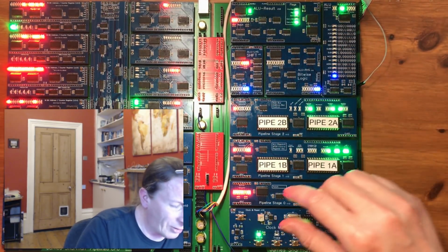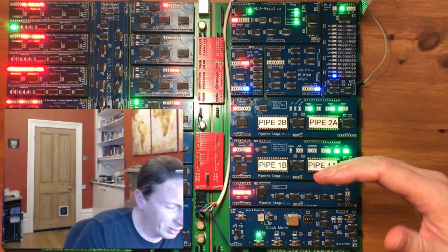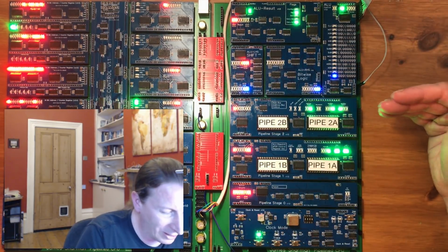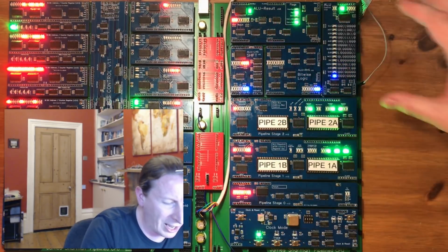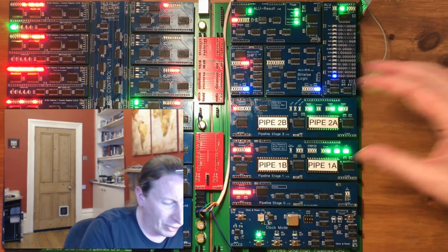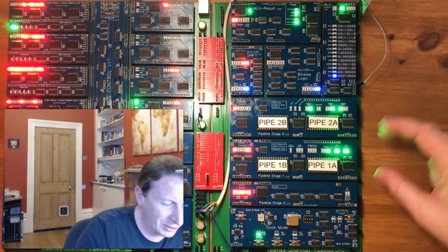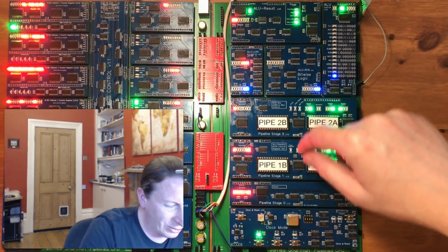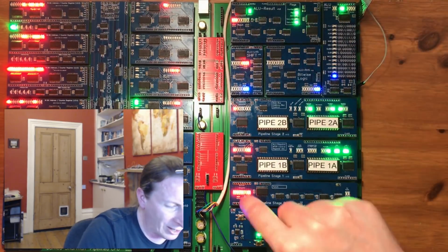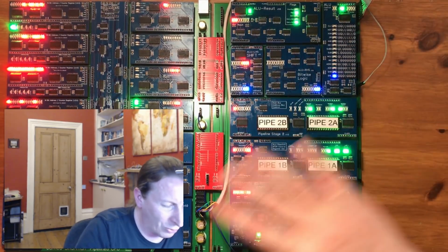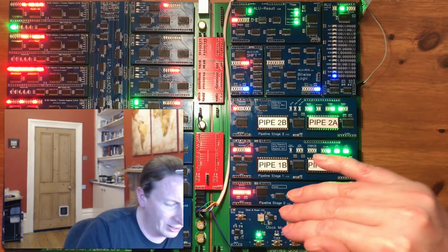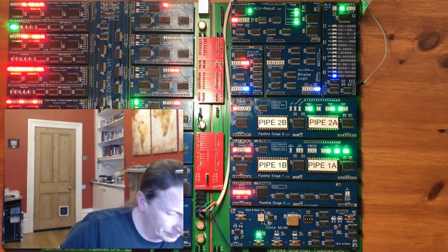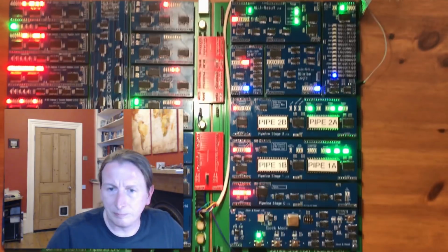Now, if I made a more complicated processor with a bunch of extra options we would need additional pipeline stages. So particularly if we wanted to extend the ALU with more complex operations that can't be done in 2 steps, then we would need a deeper pipeline in order to take the result off the end of that longer ALU. Or we'd need to do something more complex with some internal state to pick up the ALU result at a later point. Hope that answers.